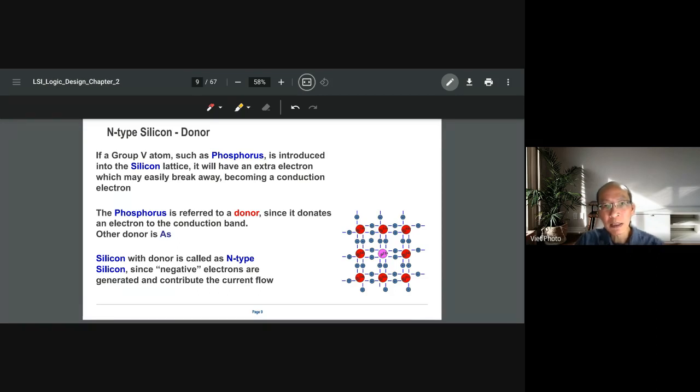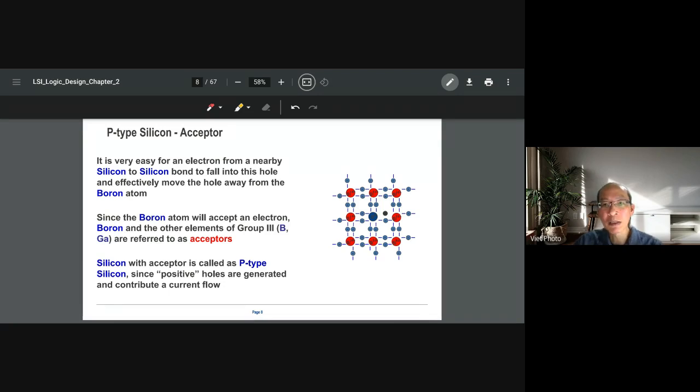When the type of conduction is by electrons, it is called n-type. Then what is the hole? When you introduce an impurity like boron into the lattice, it has only 3 electrons around the atom. Then there will be 1 hole in the lattice, because there's not enough electrons to fill it in.